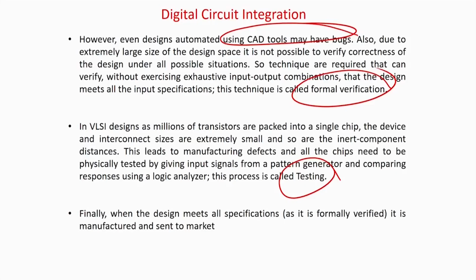So, there are two versions in software. One version is the high level implementation of your circuit in terms of block diagram, and one is the low level implementation in transistors. You just want to see whether they formally match or not. So, verification has to be done once and it is a software case.